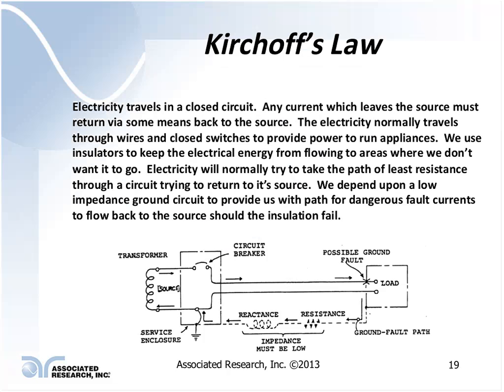Many of the UL standards, when they talk about doing a continuity check, say you can use any kind of a battery buzzer or the like to indicate the presence of ground. Some of the standards are now starting to be revised where they are saying that the maximum resistance of that ground conductor should be 0.1 ohms or less, which kind of complies with the ground bond specification also. So they're starting to be revised as some of these standards are being rewritten.